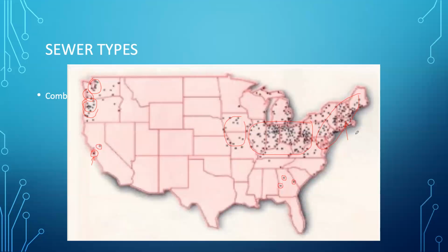So you wouldn't do a new design for these. You wouldn't be allowed to. And a lot of the engineering involved on these combined sewer systems is identifying the cross connections and over time removing them as repairs have to be made. So the challenge in the combined system is not handling the sewage. The sanitary sewage is pretty predictable.